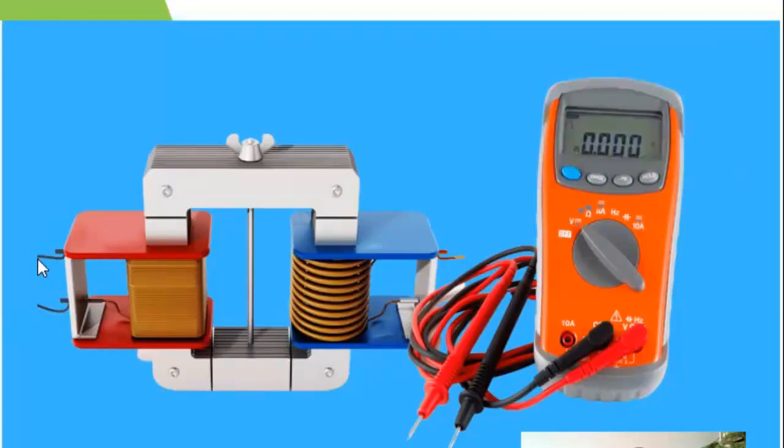You can test between the winding and ground, okay, on the primary side, and then on the secondary side you can test between winding and ground and test for continuity. You can also carry out the resistance test. Smaller windings like this have high resistance, so you can use the digital multimeter at the lowest range to test the resistance of these windings. But bigger wire has very low resistance, so you will need the milliohm meter to get the actual resistance of these windings.